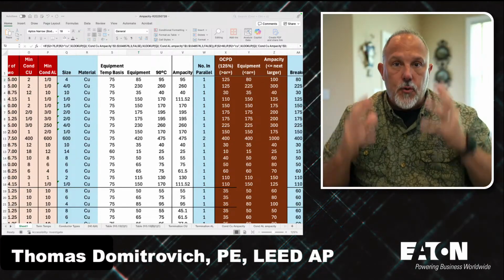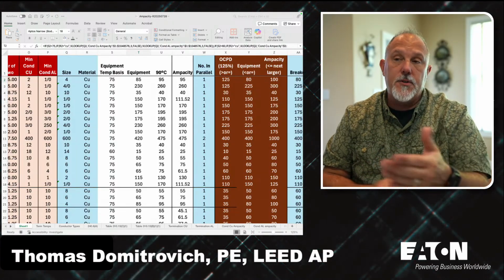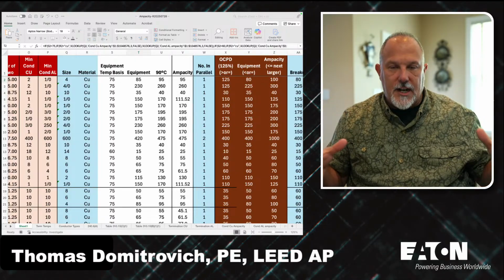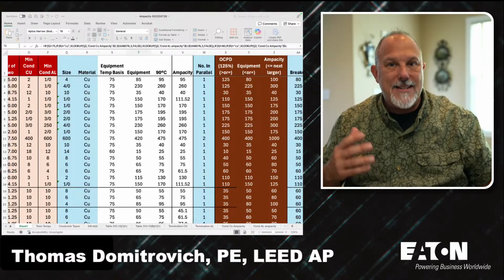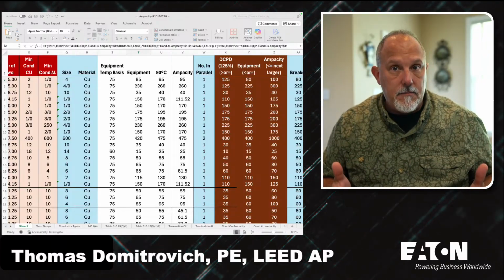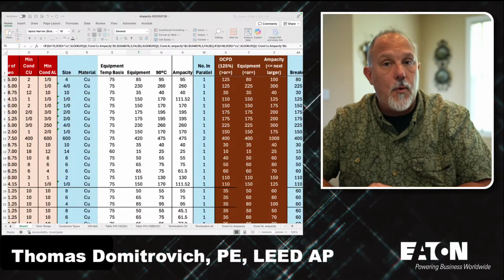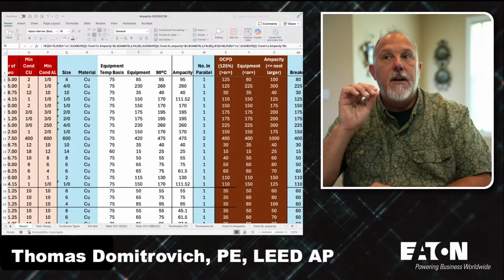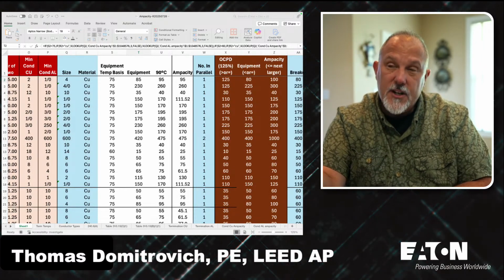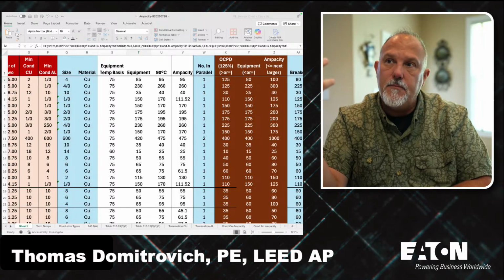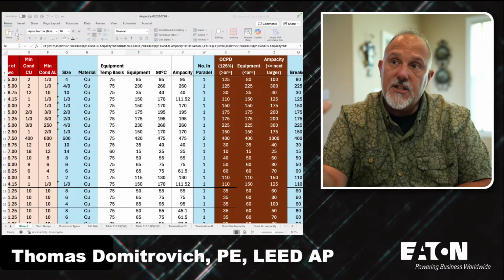It's the overall equipment rating because, especially when it comes to panelboards, we have to think about the enclosure size and all of the other components that are associated with that panelboard as an assembly, and do they work as a system? And if they work as a system, they're tested as a system, and temperature is one of those aspects of difference between the component standard, because I may be able to get a circuit breaker to pass a thermal test, and say it just barely passes.